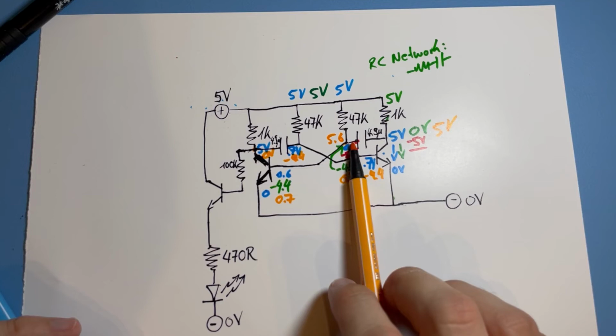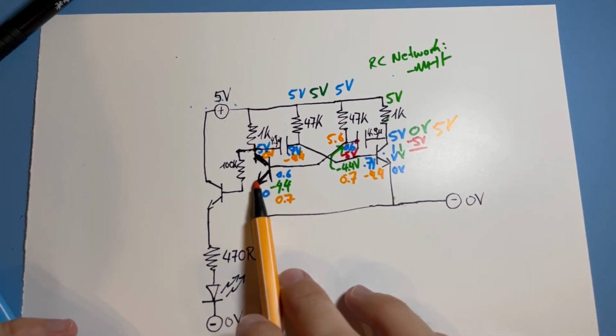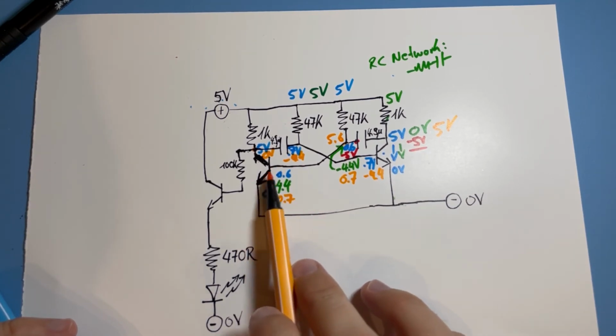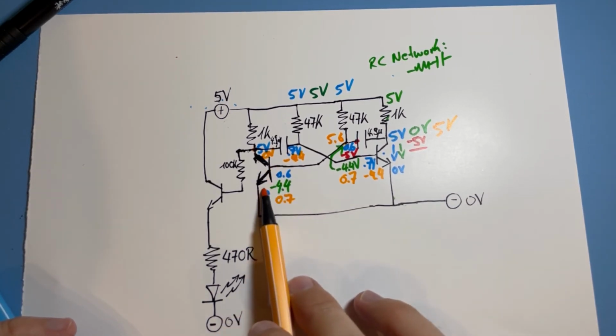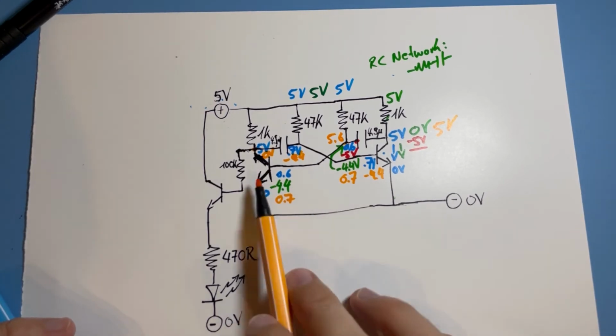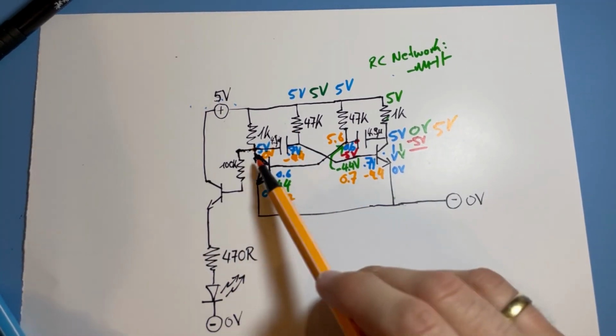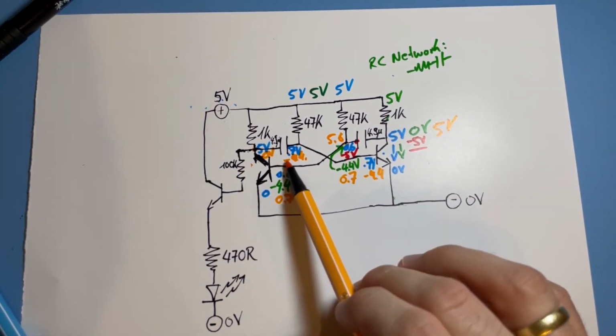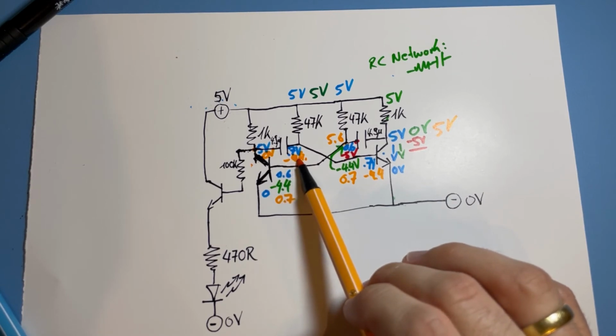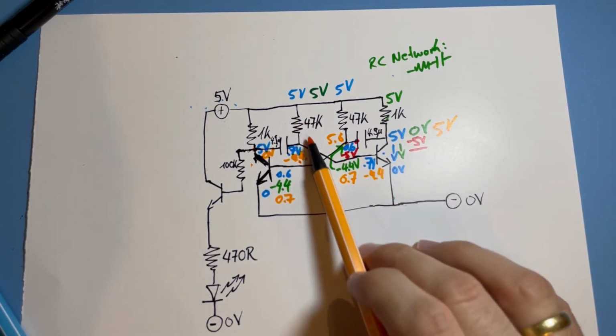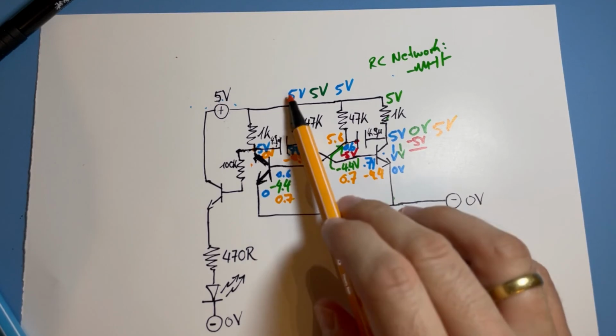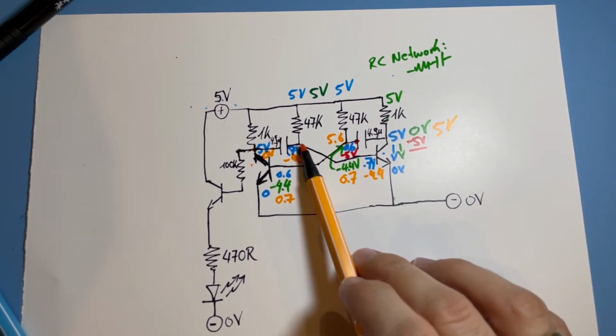I'm sorry for that. And so let's watch again to the left our transistor and the base emitter path. Base emitter is positive, above 0.7, and this still is conducting, of course. And what happens again is the game starts again. You have now here minus 4.4 volt, which needs to build up to 0.7 volts slowly over 300 milliseconds.